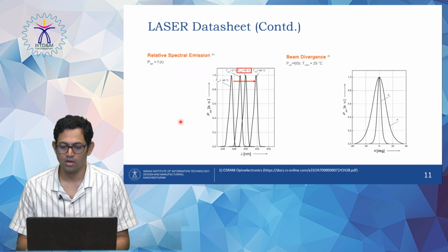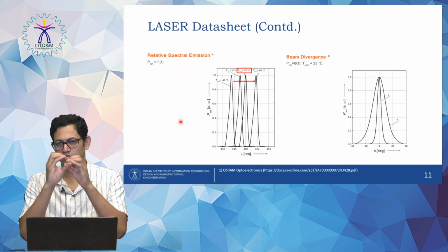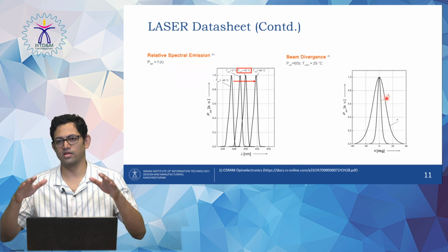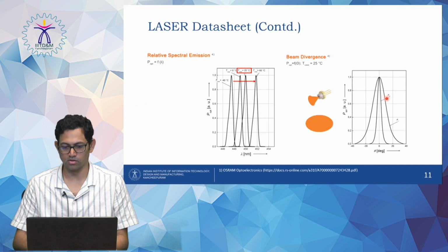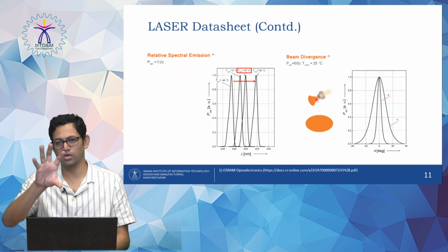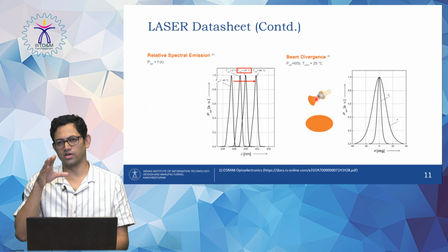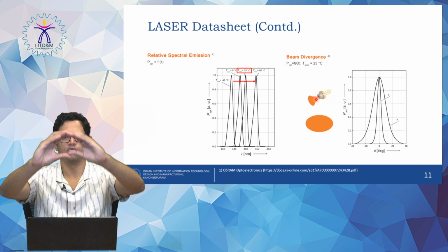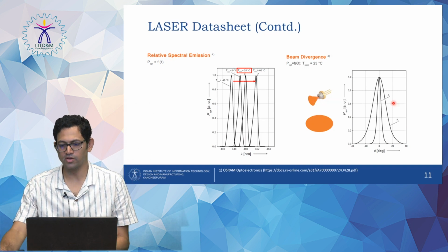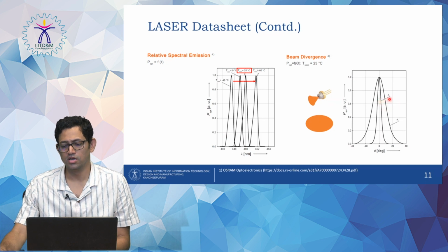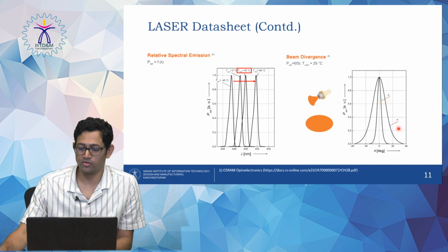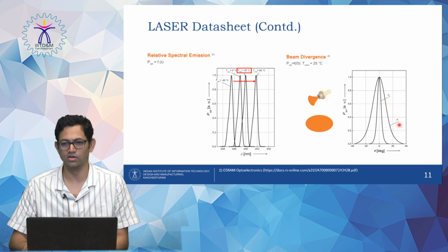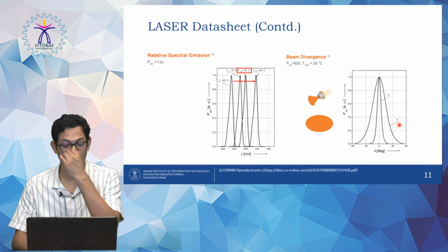And at the same time we can see that the beam divergence is not completely cylindrical, but has its own axes, that is a parallel as well as a perpendicular axis. So you can see that the laser is not emitting a perfectly circular beam, but rather an elliptical one, which is moving forward. Okay. And that's why with the beam divergence you can see theta parallel as well as theta perpendicular, both the ellipse minor and major axis, giving both the degrees of viewing angle.